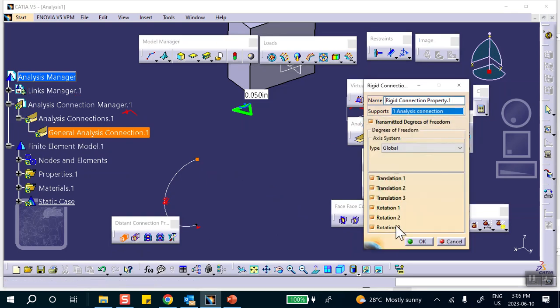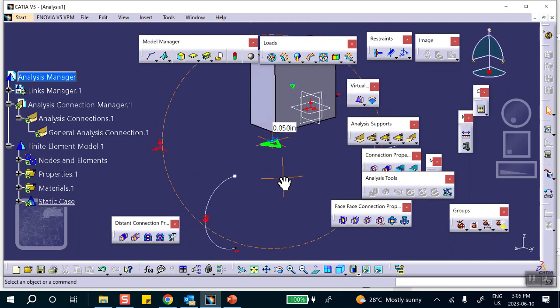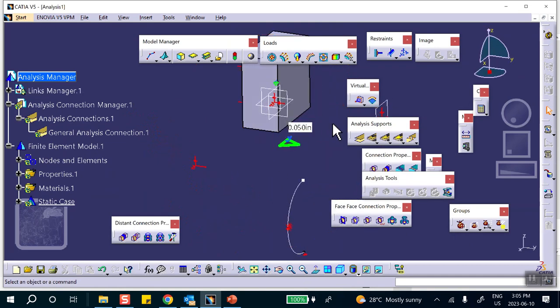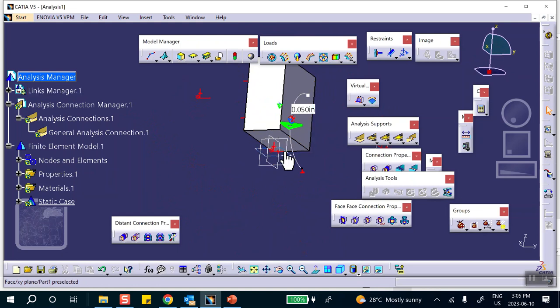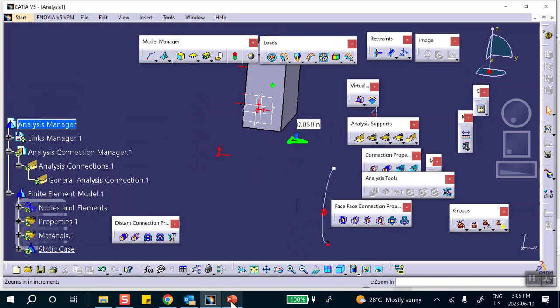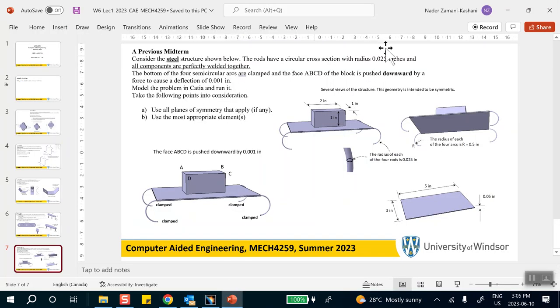And because this is not a cable, all of these just stay. Now, the other thing is how this thing is placed on that sheet. If it's fastened, then you create a connection between here and the surface, make it fasten. Or if you just took it and placed it there, make sure it doesn't slide either way. If you read the problem description, it says all components are perfectly rigid, perfectly welded together.